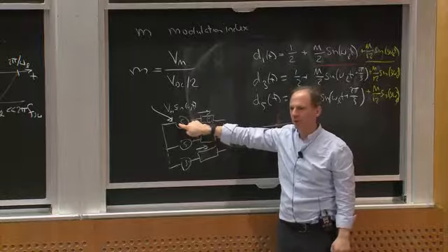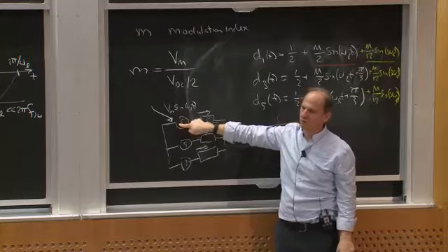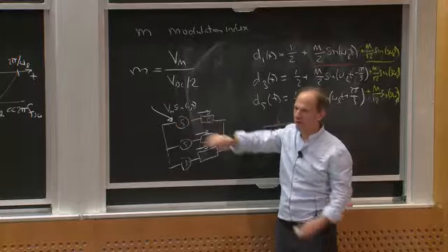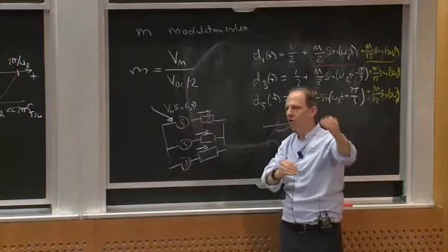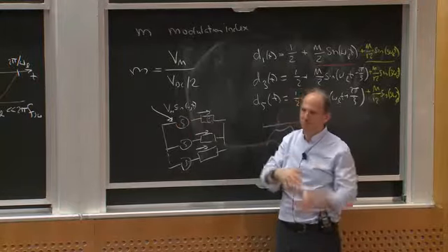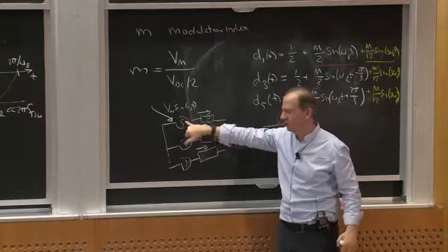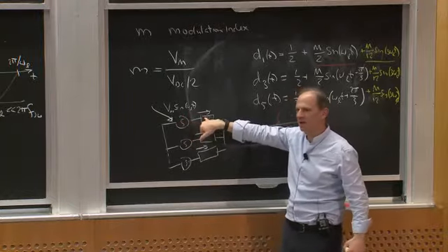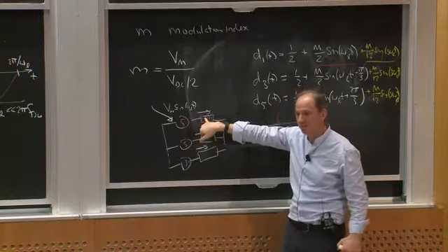And the problem with not doing this third harmonic trick is that if I try to turn up the duty ratio more, I get a lot of low frequency harmonics. I get third, fifth, other content in here, which is then going to drive low frequency content in the machine.